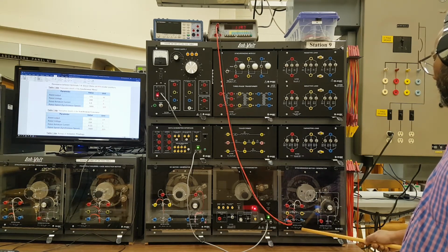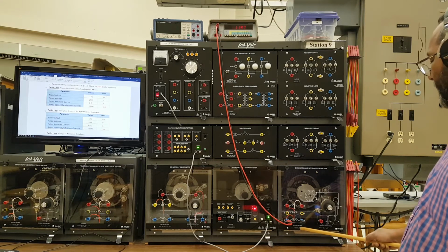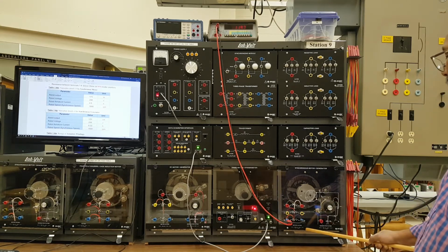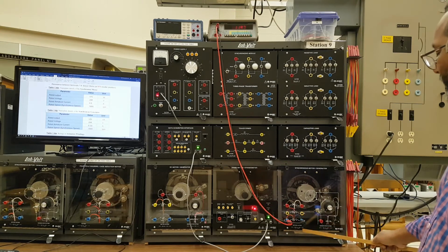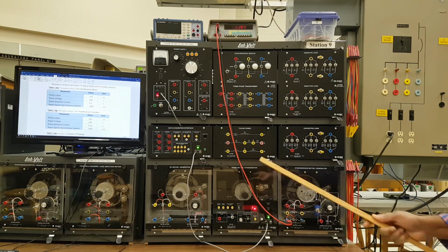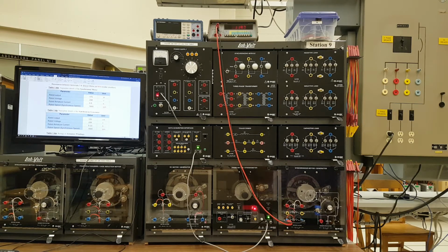When you design for both motor and generator, you take the highest value. So instead of 0.33, you will design the wire for 0.8 amperes. If it is able to withstand 0.8 amperes, then 0.33 is taken care of. And now, why is this 1 ampere instead of 0.8? There is a safety factor for everything in engineering.